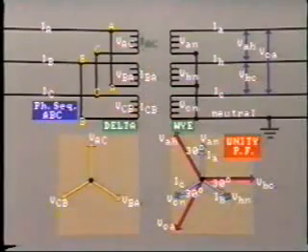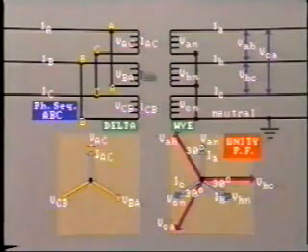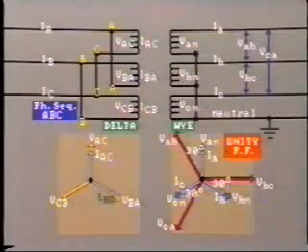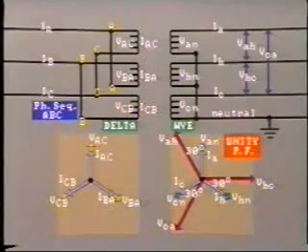Therefore, IAC is drawn on the phasor diagram in phase with IA, and IBA is drawn in phase with IB. Similarly, ICB is drawn in phase with IC. But what is the current in line A, that is IA?